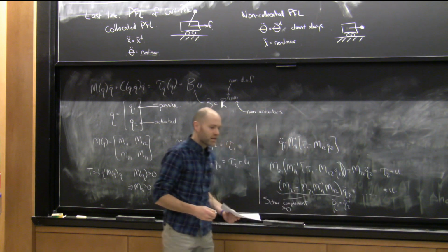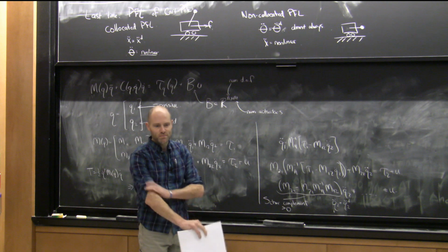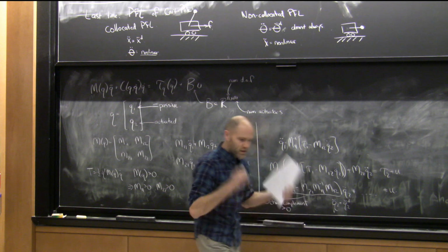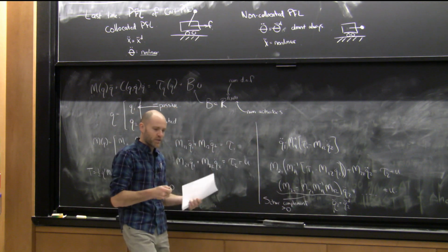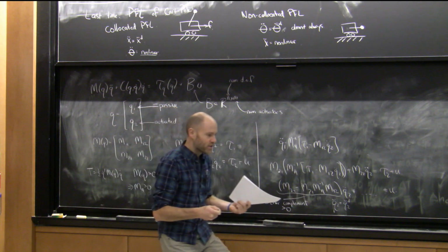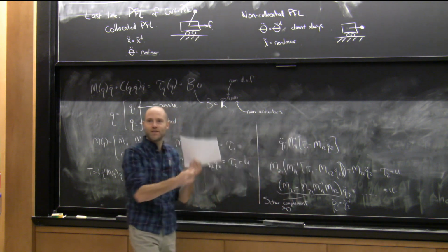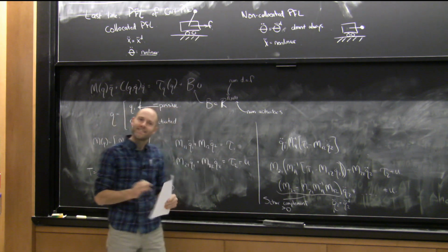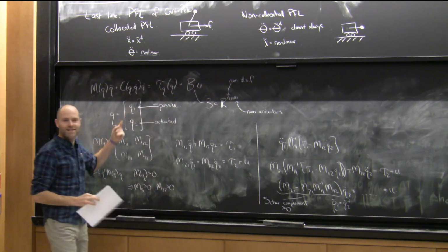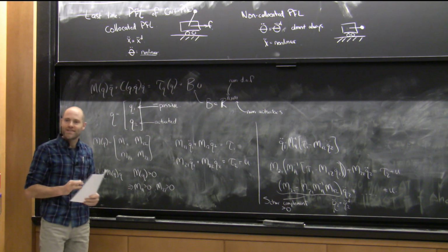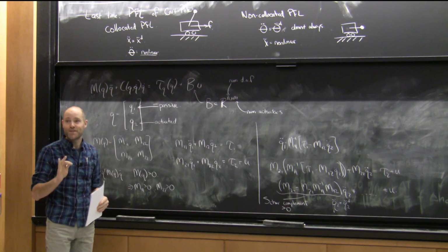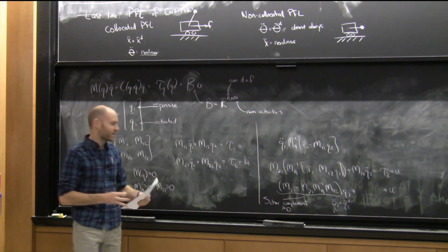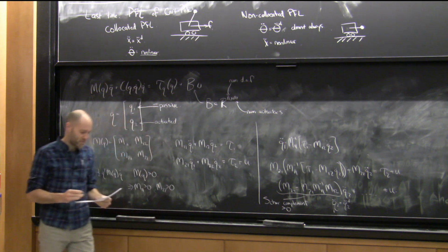But, you know, Asimov is very advanced, it wouldn't do this, but there have been robots out there that have proofs saying that we're guaranteed to follow the desired trajectories, but they only talk about the actuated joints. So it could go like this, but then you go over and it would still be going through its motions perfectly, canceling out gravity, but it might be upside down, right? So it's like, well, if you haven't said something about those joints, which are the center of mass and orientation, then maybe you don't have a proof. You have to watch for that. In the walking world, people say "provably stable walking controller," and then they're only controlling Q2. It's kind of a pet peeve.